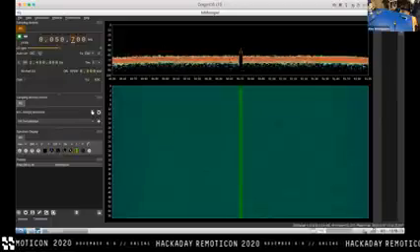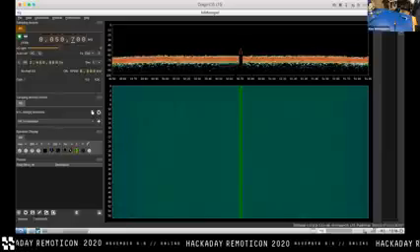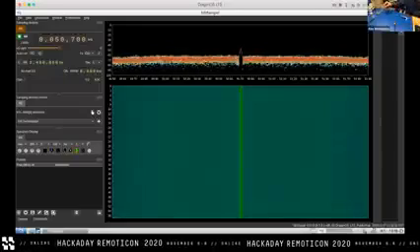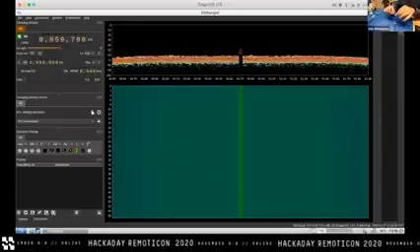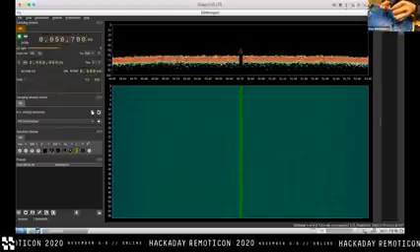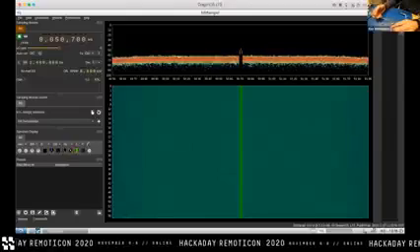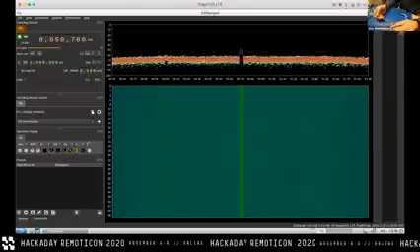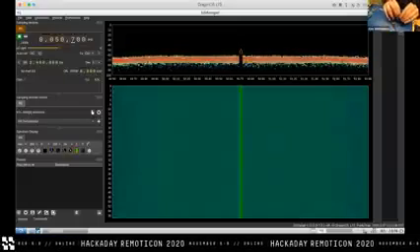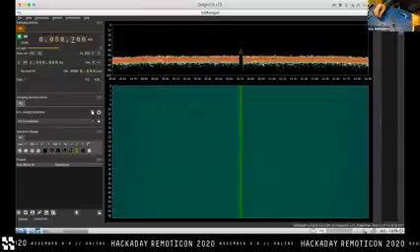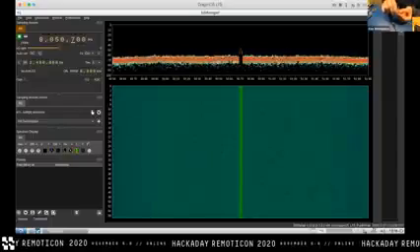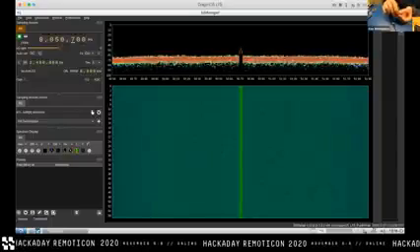So we're back over here, spinning the waveform. Okay, so we've got 50 megahertz. 50 megahertz is over here. So we already know that I basically just attached a PLL output on the chip to some pin over here. And if we start waving this wand around, this one has very limited range, you know what, we're just going to start with the big one. Do it the way that we would expect. We know from the test report, the imaginary test report in this case, that we failed on some 50 megahertz noise coming loudly from somewhere.